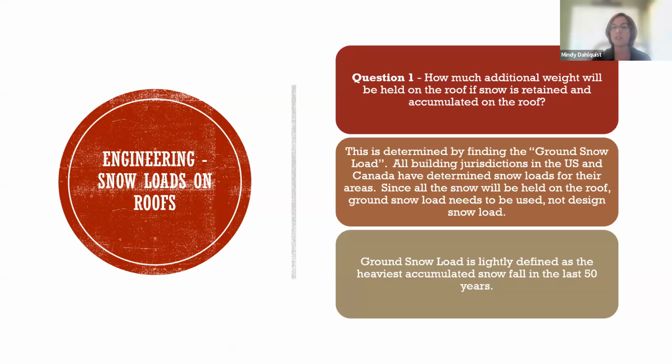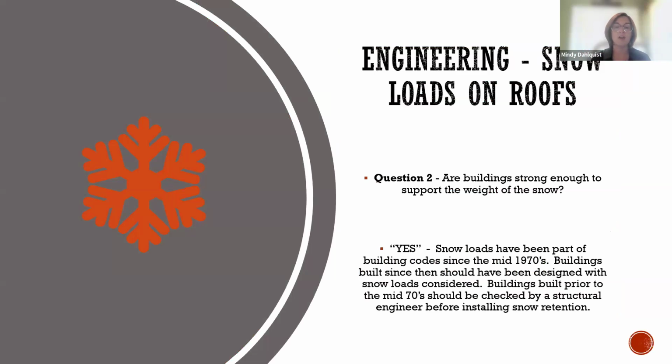And since all of the snow will be held on the roof, ground snow load needs to be used, not design snow load. And then, are the buildings going to be strong enough to support the weight of the snow? Well, snow loads have been taken into consideration in building codes since the mid-1970s. Any buildings built prior to that definitely need to be checked out by a structural engineer before installing any kind